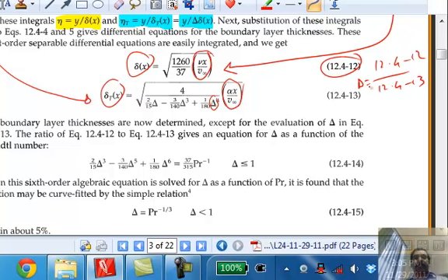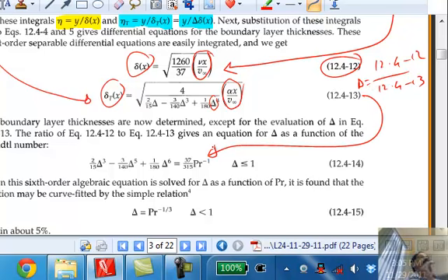So by dividing that one by the other and squaring it, you can simplify that equation into this equation, which is now parameterized in terms of Prandtl number. So if I know the Prandtl number, I can solve for this. So the procedure for computing quantities: your starting point would be this equation. You find out what the Prandtl number is, because that's given by the fluid.